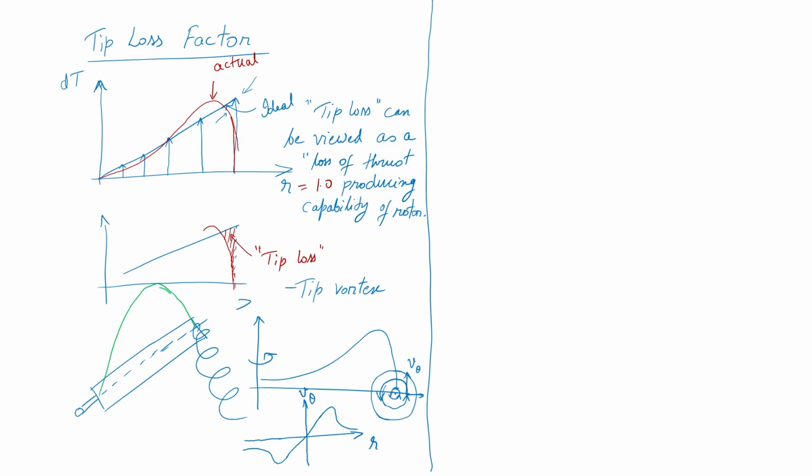Okay. So, if you go from the core of the vortex, the speed will be 0, as you go outwards it will build up and then again come down. Okay. So, you are going radially outwards from the core of the vortex. So, this is just to give you an indication of how, if you go inside a tip vortex, what kind of flow field you will experience there.